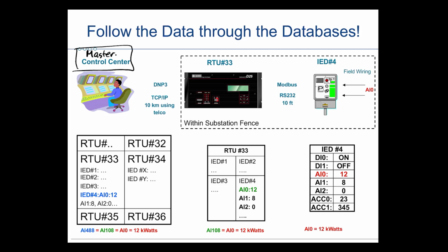Notice how then when it comes to the wide area network connection, we're using a SCADA protocol called DNP3, and we're going to look at it later. And this is really a true SCADA protocol designed for wide area networks. So we've got a DNP connection out to all of these remote sites, or these server sites or slave sites.